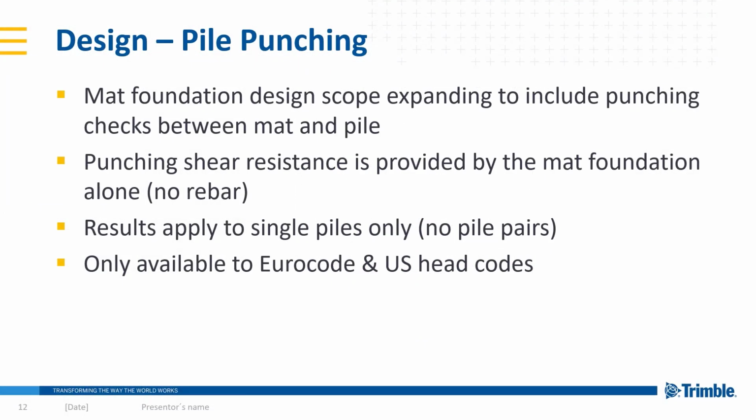So the final topic I'll talk about is the pile punching shear check. In the program, for the last few versions of Tekla Structural Designer, you could design foundations, including mat foundations. Within mat foundations, you could always design piled mats. One of the limitations previously for piled mats was that the punching shear check between the piles and the mat foundation could not be checked. So those checks usually had to be performed externally, either based on the pile capacity or the force in the piles.